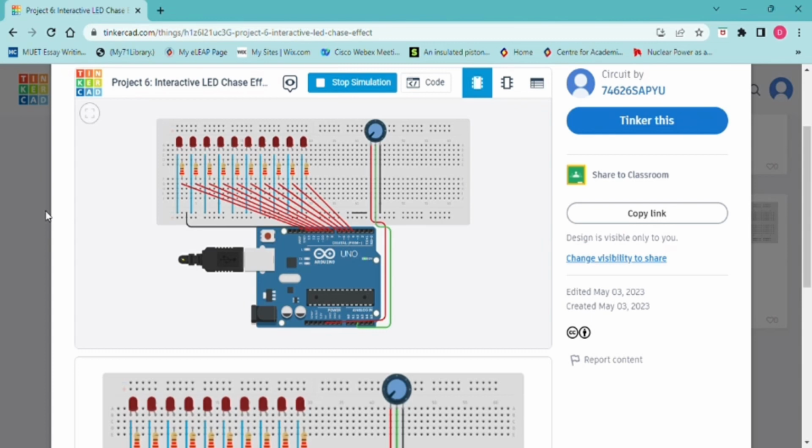Now the potentiometer has 3 legs. By connecting up just 2 legs, the potentiometer becomes a variable resistor. By connecting all 3 legs and applying a voltage across it, the pot becomes a voltage divider. This is how we have used it in our circuit. One side is connected to the ground, the other to 5 volt, and the center pin to our analog pin.